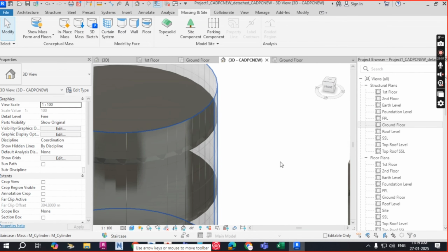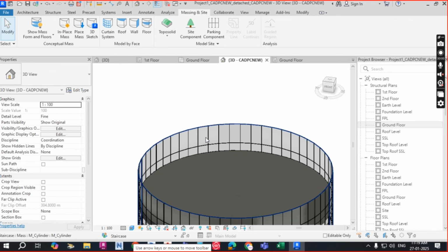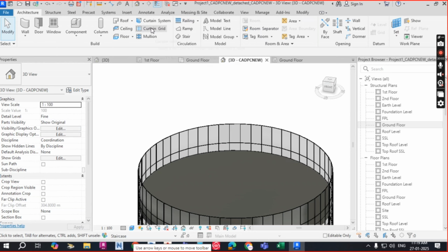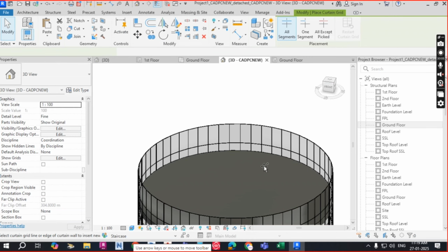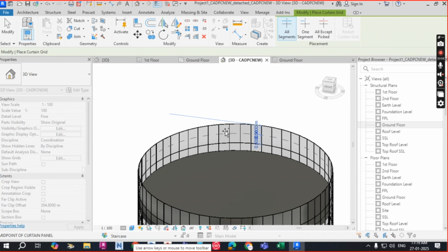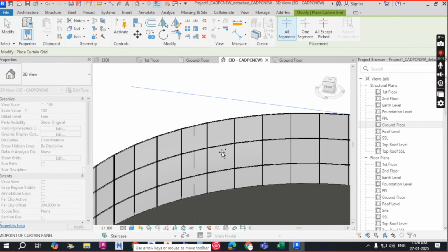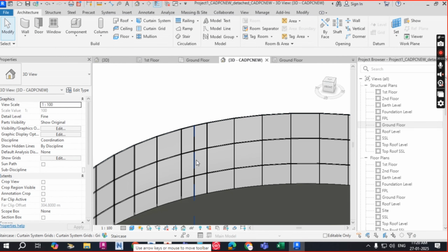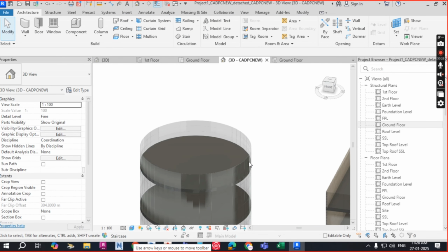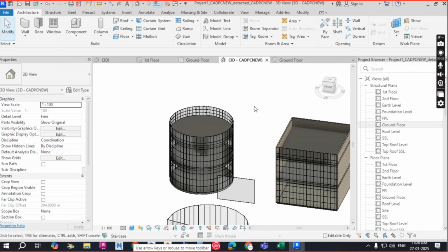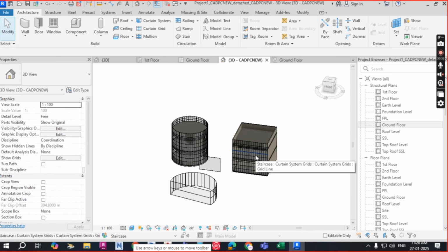So after applying this material also, if you want to make any addition, that is also possible. You can edit also. So you have to put curtain grid. If you say I want to bring one more glass here, you can make it a grid. Just click, it will become a grid. If you want to make one horizontal break also here, a vertical break, that is also possible. You can see. So you can break it, make movement, modification, everything you can do, because after applying the material, it will become a normal model. Okay, so this is an existing family.